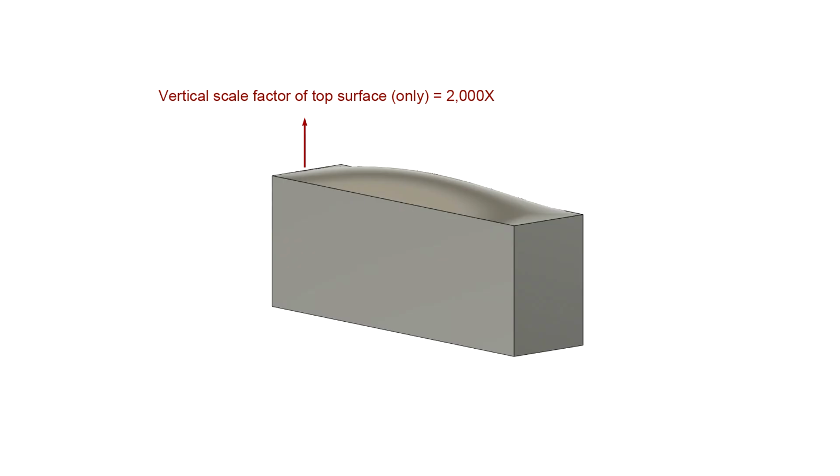try that. From what we've discussed so far, we might place an optical flat on top of the block with the flat parallel to the nominal part surface, as we just saw. In the side view, the plane spacing is scaled with the same scale factor of 2000, so the planes are still spaced at 1/2 wavelength of the scaled model. Just to check the scaling, the convexity of the block surface is a bit more than 1, 2, 3 half wavelength planes high. At 12 microinches per plane spacing, that's 36 microinches, and adding a bit more gets to the 40 microinch height we modeled.